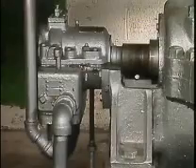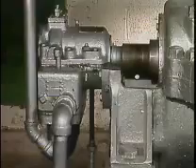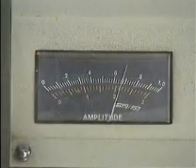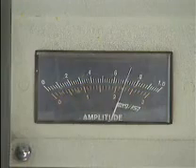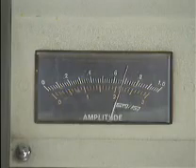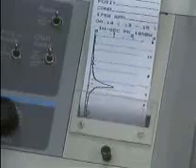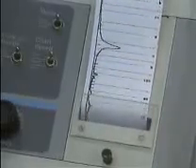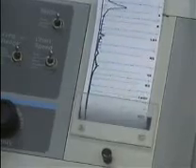However, even small changes in a machine's condition can produce large changes in the amplitudes of its vibration characteristics. A machine that has a developing problem invariably shows an increase in the amplitude of one or more vibration characteristics. An important part of analyzing vibration data is comparing it to information known as baseline data. The term baseline data is used to describe information that is collected to use for comparisons with future readings.